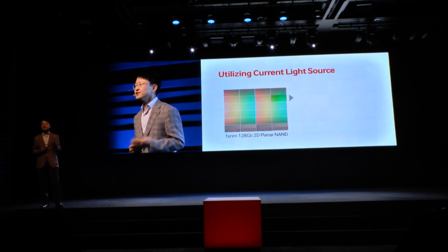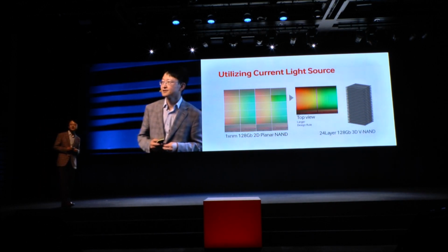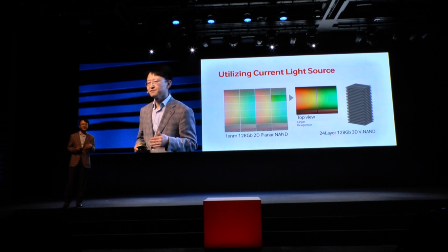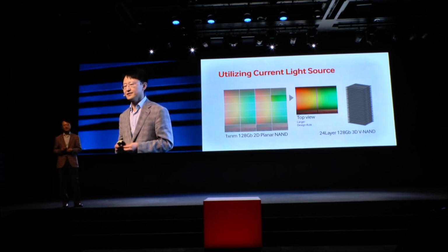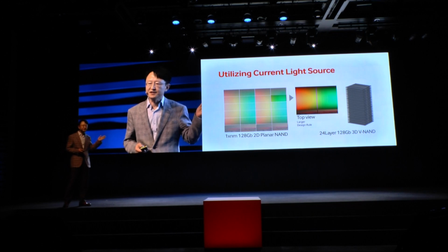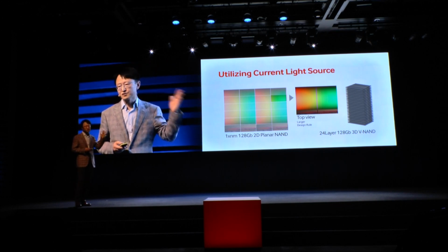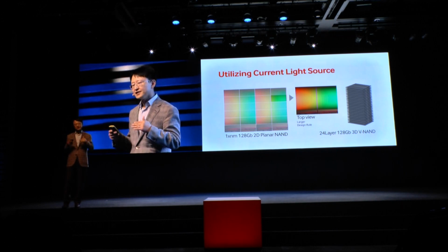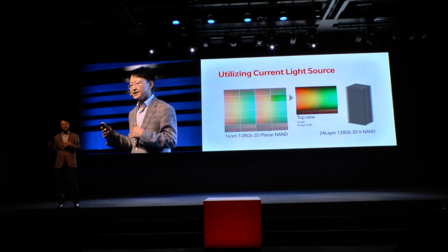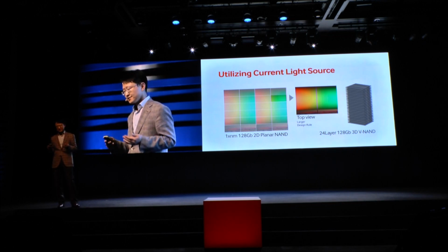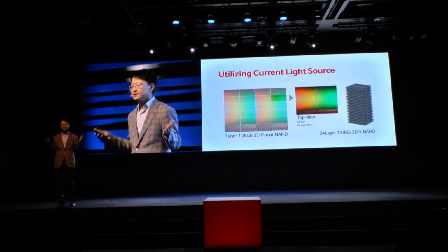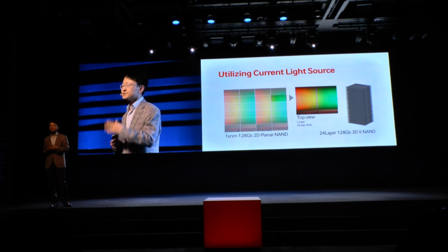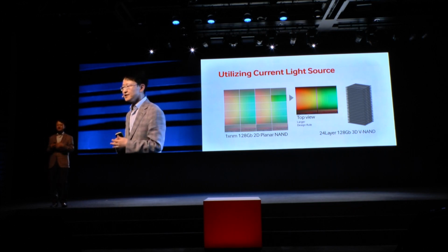As I mentioned before, shrinking needs a sophisticated light source. But for V-NAND, we don't need it. The reason is the design rule of V-NAND is several times larger than planar. For example, take one piece from the array, in this case 1/24, and make it 6 times larger, and stack it layer by layer. That's it. The left side and right side have the same density of 120 gigabit. But compared to planar flash NAND, the design rule of 3D V-NAND is 6 times larger.